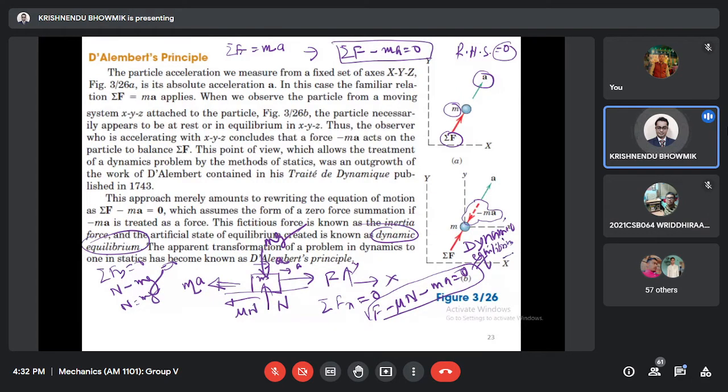So on the right side it is 0, and whatever direction the inertia force acts, in the reverse direction we consider some pseudo force in the free body diagram. Many times this consideration can eliminate some confusion in drawing the free body diagram.